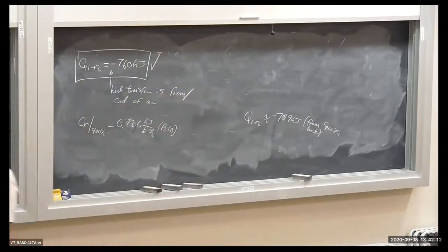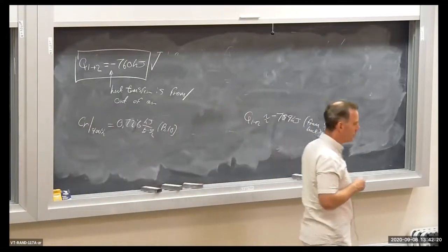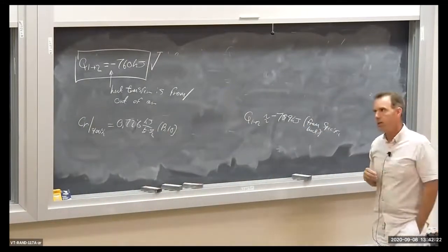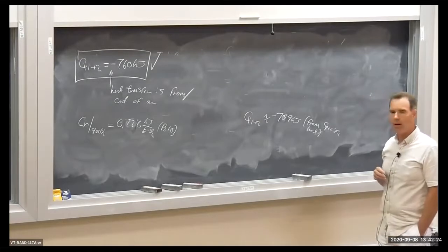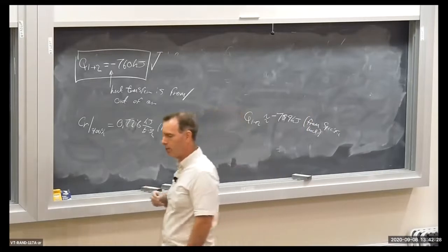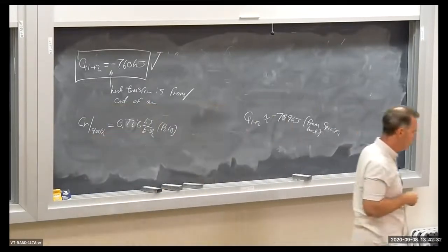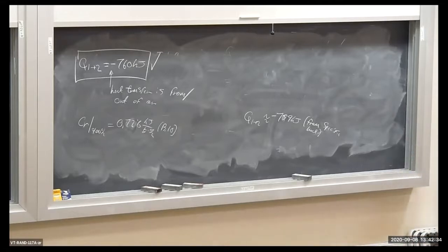If you want to go through and check that IGB, the ideal gas behavior, is valid, I think you'll find that it is. The minimum temperature in the system is 300 degrees Kelvin. The critical temperature of air is what, 133 degrees Kelvin. So you're going to get a reduced temperature minimum greater than 2. And I think you'll find the pressure is what? What's the critical pressure for air?